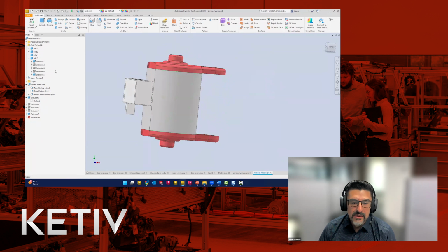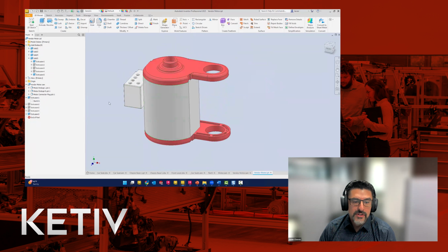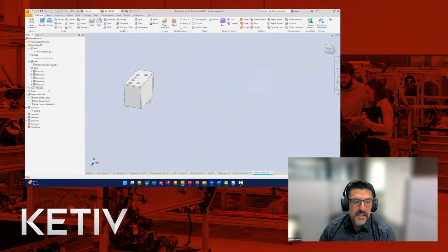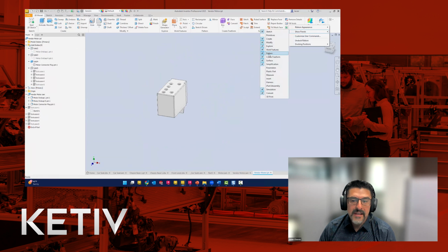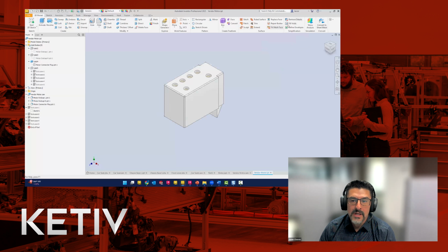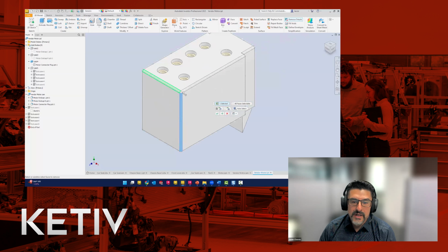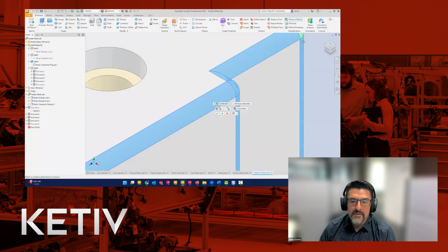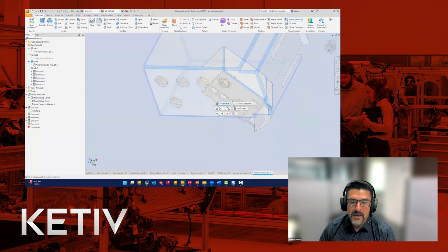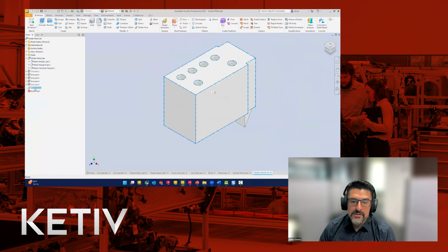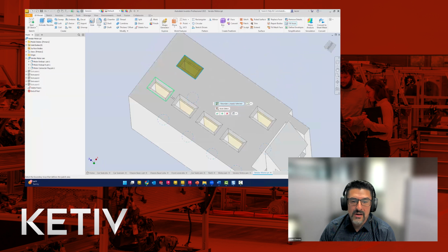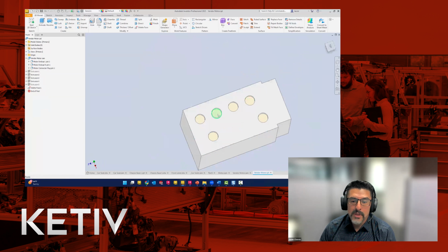It'll be a series of similar processes. For the most part, I want to show you more tools that are available in part mode. So in a moment, we'll go ahead and isolate the male plug. And we want to maintain a lot of the detail here. So when you're in a part environment, if you don't see the simplification tools, you could go to the panel and bring these out. And there are tools there to remove edges, rounded-off edges, and make this more squared off and simplify this. In addition, there are also tools to start eliminating voids. So there is a void inside of this with all kinds of detail. We don't need it. We're going to plug this up and fill it up, if you will, as if there's nothing inside, just by plugging up the holes.